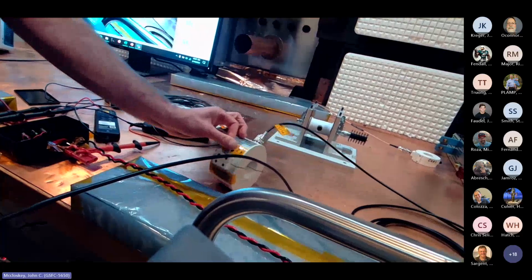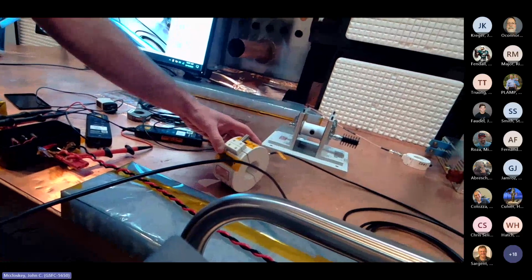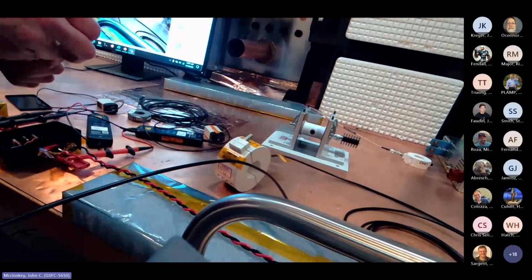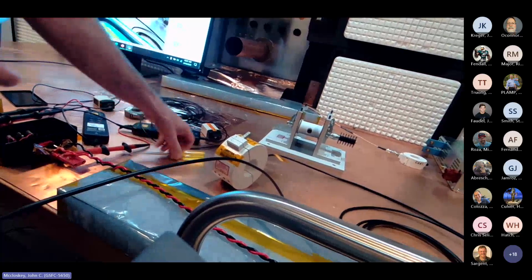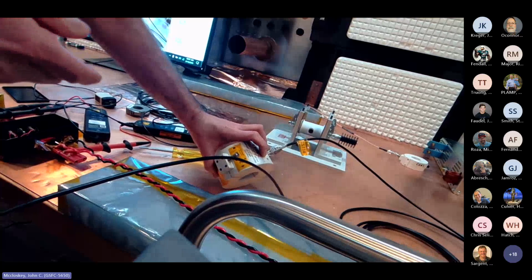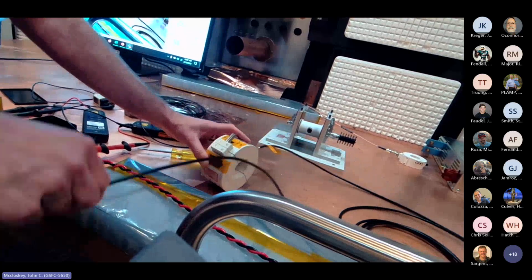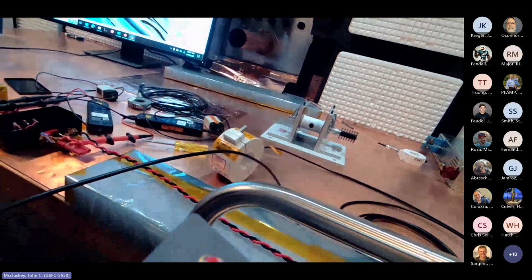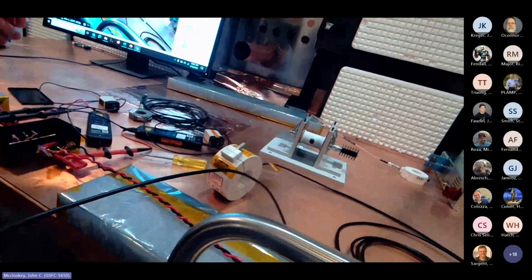Now with RF, when you're dealing with tenths or hundredths of a dB, that's much more crucial. But still, it's a good practice. Leave it connected if you can. Not the end of the world if you have to disconnect it, but definitely use the same cable and all the same drive circuitry. That's part of what you calibrated.